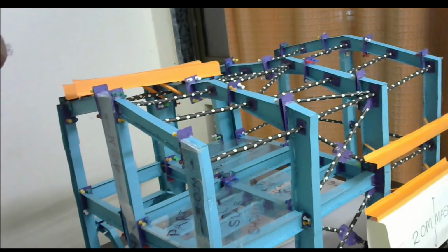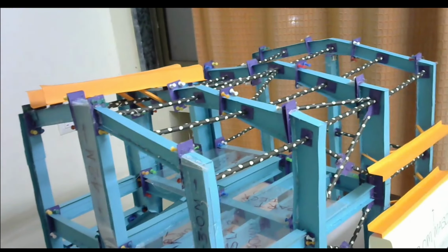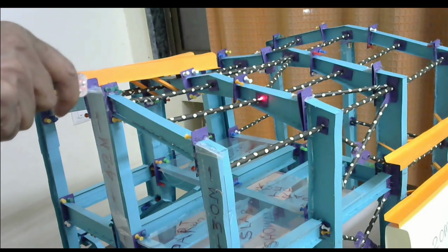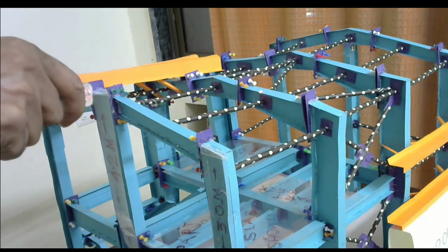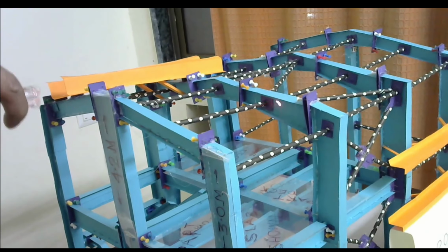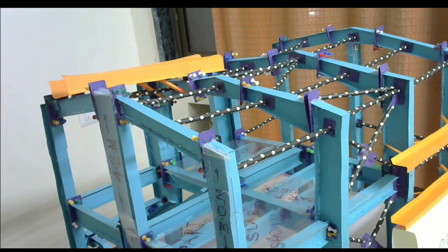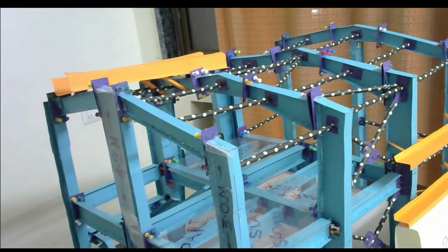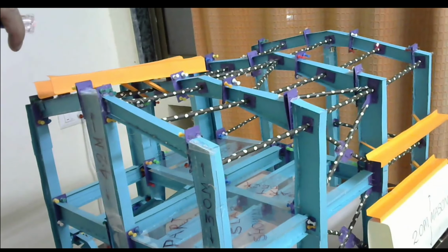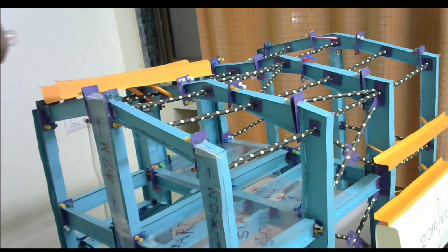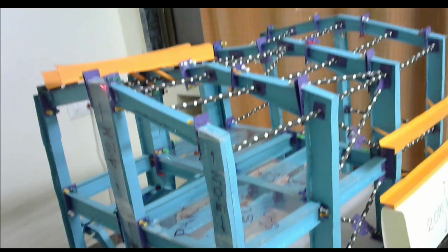Now if suppose there are no flange braces, what will be the LX and LY? Now there is resistance at this point, at the half of this. So 6.1 meter divided by 2 is 3.05. So LX and LY will be 3.05 if there are no flange braces. Same is the case here. Same is the case for this part.